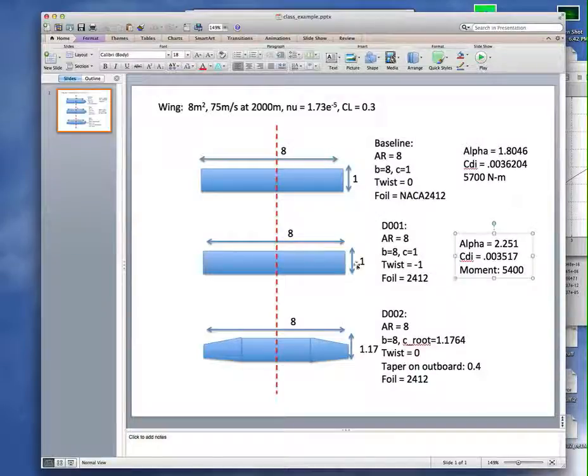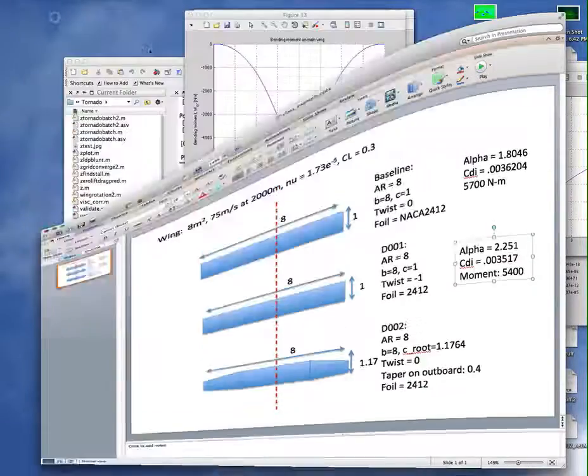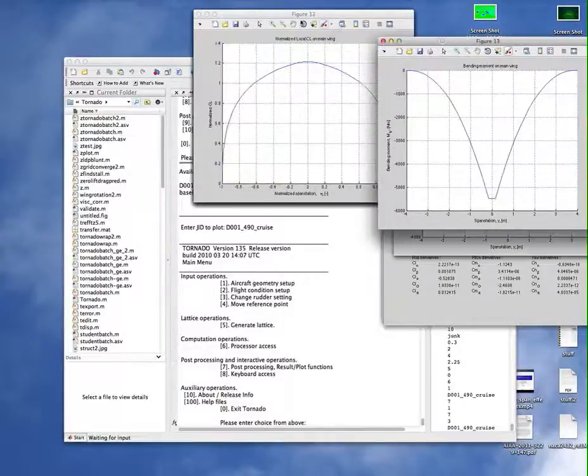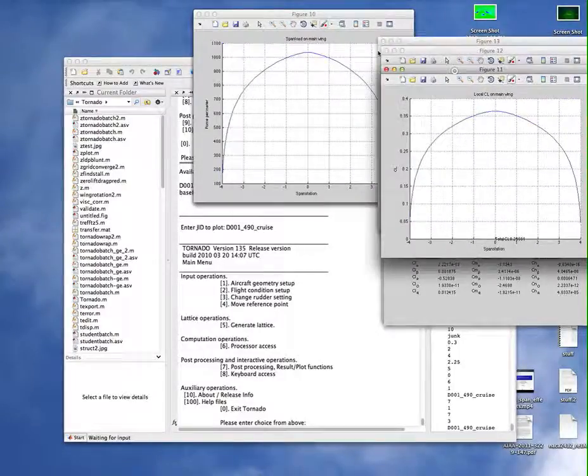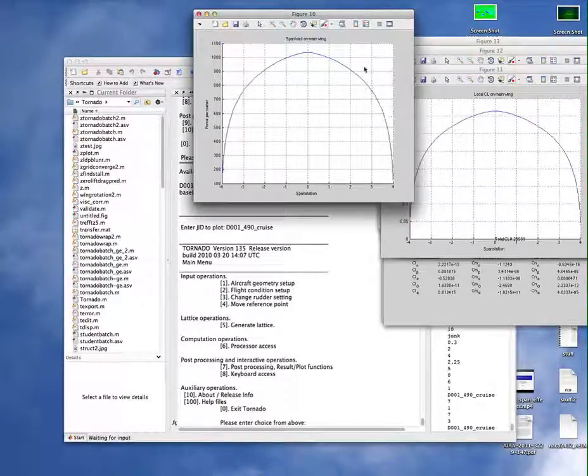That's because I moved the load, the span-wise loading, which let's quickly look at here. So bending moment, normalized CL, local CL, span-wise loading, and I'll compare the two at the end here, but the original load was much squarer. Now I've squished it so most of the loading is near the fuselage and away from the tips. It's not elliptical, it has a kind of fun hump to it, but it's closer to an elliptical distribution.